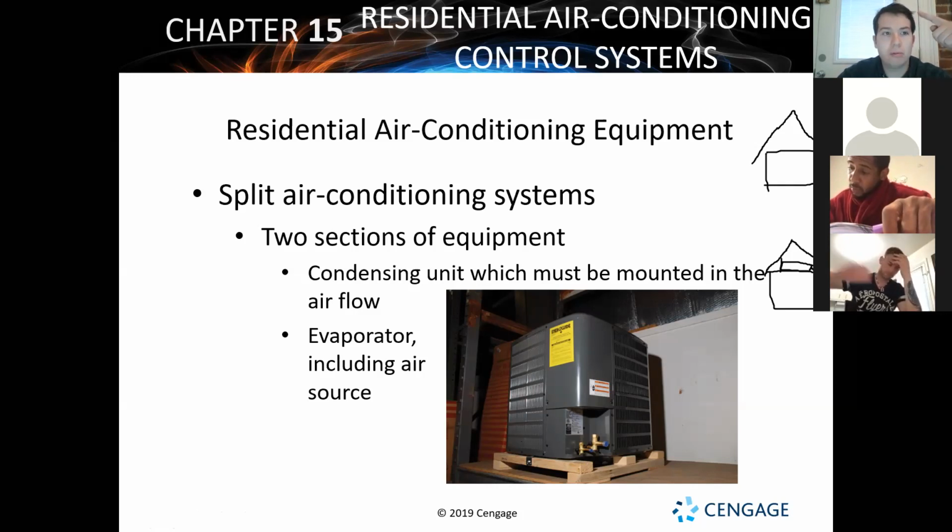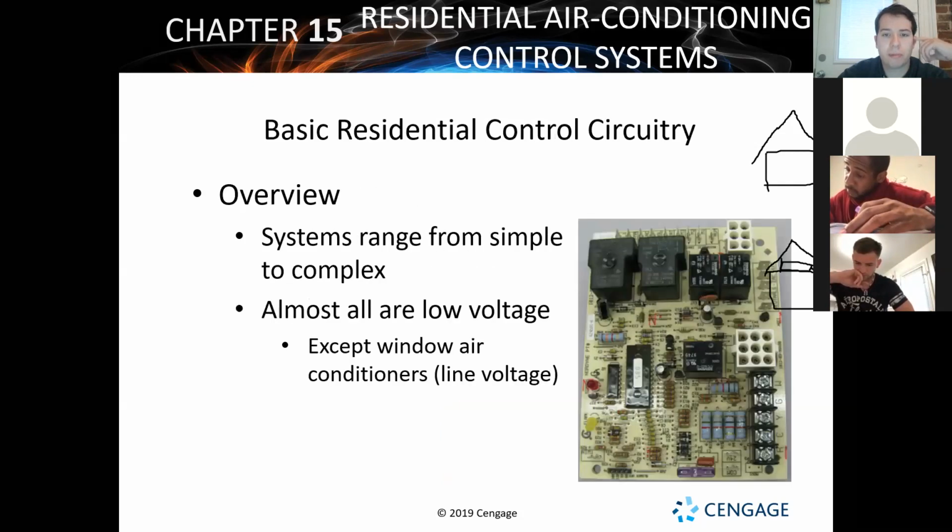A yellow for your call for cooling, so it says, okay, go into cooling mode, and on the other side of that contactor, you need to run a line back to common on the 24 volt side so that it can complete that full circuit. It can have 24 volts come in, go through a 24 volt load, like that coil, and then return back to neutral common. And that's what we're typically going to see a lot of times for an outdoor unit. So there's some basic controls y'all see pretty consistently.